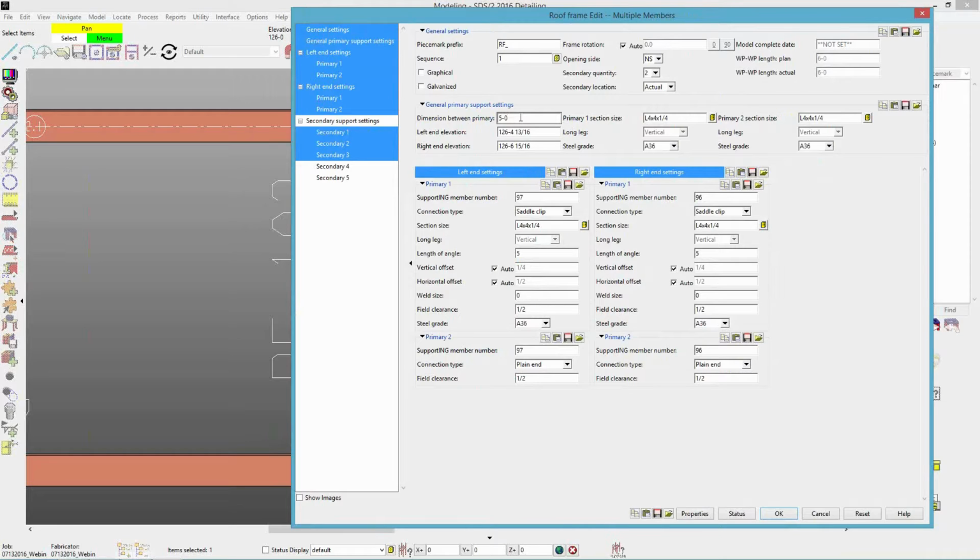So I would add 4 twice, so 5 foot plus 4 for each primary angle, and then add the overhang, which in this case I'm just going to say it's going to overhang 1 inch, so add another 2 inches. So we got 5'8" plus the 2 inch overhang. The length of my saddle clip down here would be 5'10".